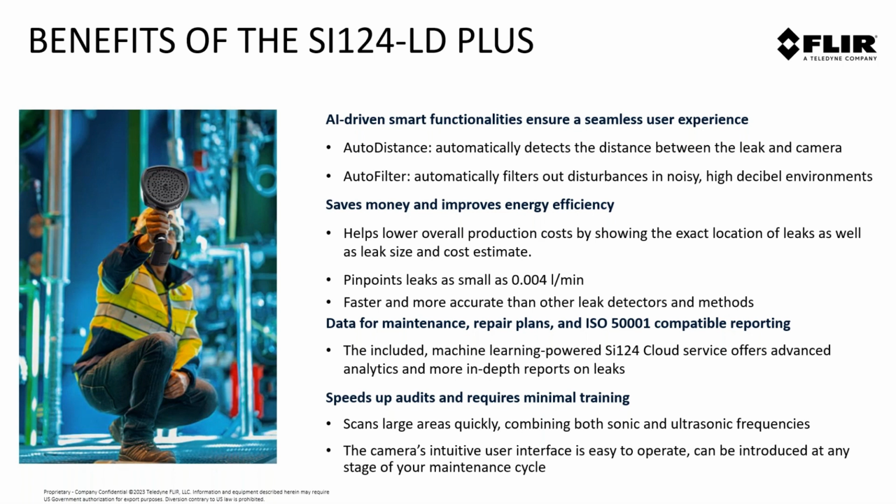Simple things like being able to perform auto distancing or auto filtering, to clear out any noise that's not germane to where we're actually shooting directionally, to understand where that leak is and how big it is, and ultimately save money and improve energy efficiency. The real power of the tool is we're able to find leaks as small as 0.004 liters per minute, very small leaks.